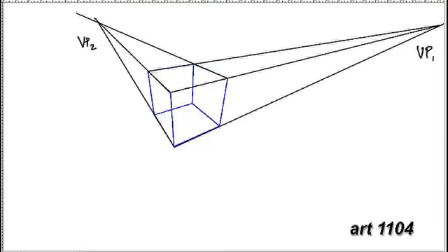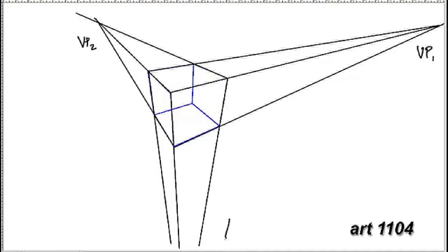But in a 3-point perspective, obviously there's a third point to consider, because as our station point and our position has moved higher than the geometry in the scene, the vertical lines are now looking like and need to be depicted as converging lines as they recede into three-dimensional space. So this is my buildup of a 3-point perspective.